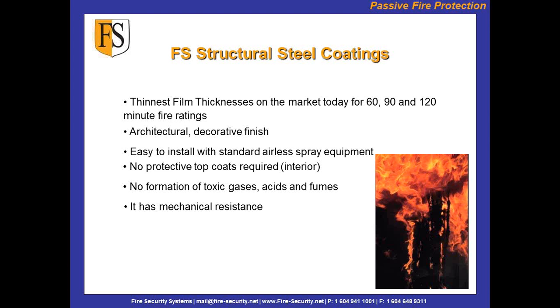Sometimes it's so hot that you can't even spray the product properly because it's curing in the lines of the machine. I have seen that happen at 45 and 50 degrees Celsius. But then again, you'd be mad to be spraying that outside anyway. But it does happen. It happens everywhere with every type of coating. If the temperature is simply too high, you cannot spray it, especially solvent-based. Solvent-based aren't curing, but the water-based, yes, they are. The water in the water-based coating is evaporating at that sort of temperature before it can even get sprayed on.